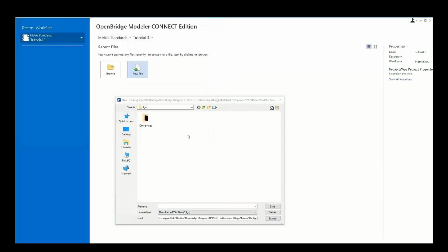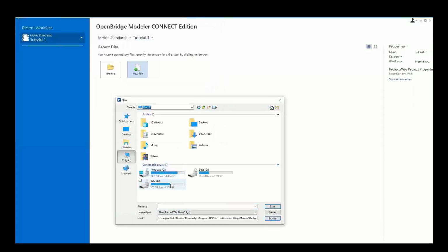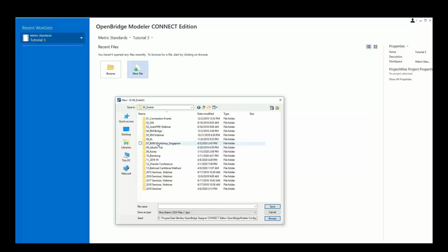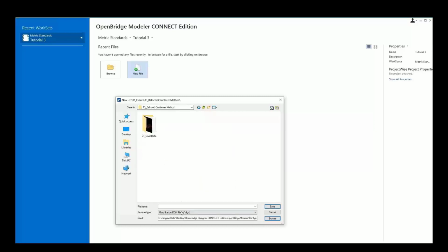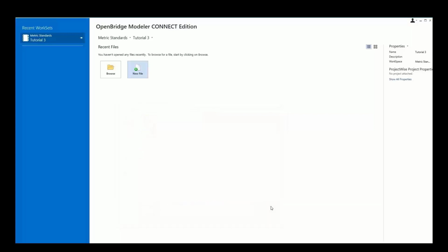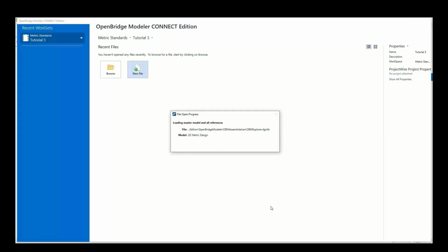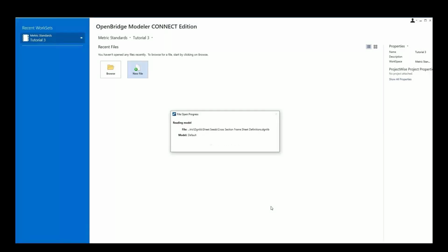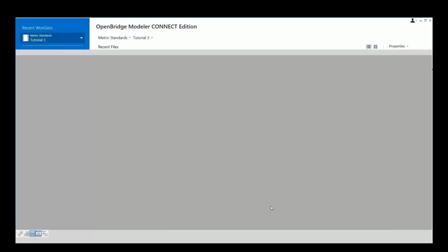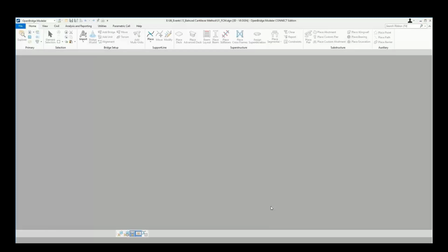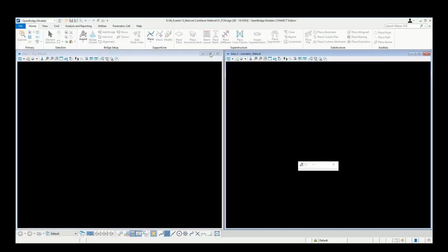Select the DGN file and define the file path and name to save this model. The DGN file has information like design unit, category of line, text style, and label. And an empty model file is created.